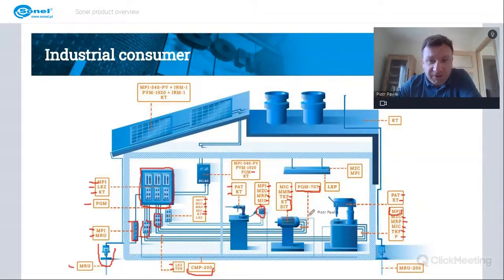Now, further on, when we get to the building, we can find the light. So here we can check the short circuit loop between the cover of the lamp and the ground channel. For that there are meters of MZC series, so for short circuit loop measurement, or this is one of the functions in the multifunction meters MPI series.